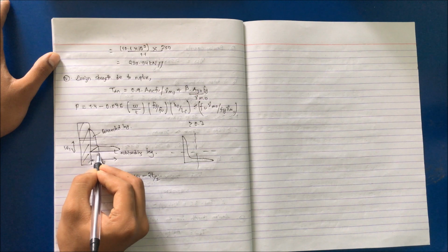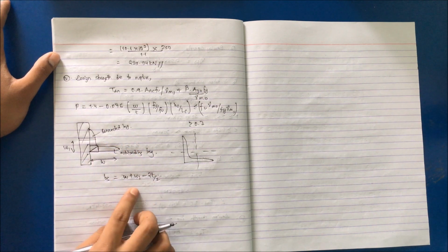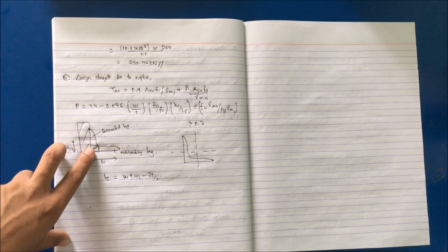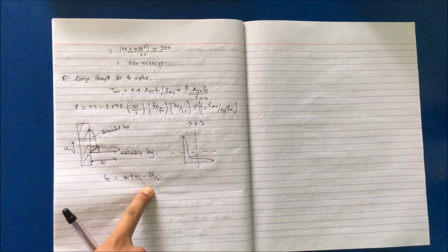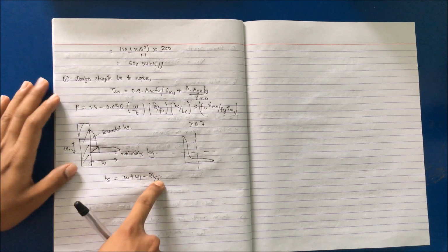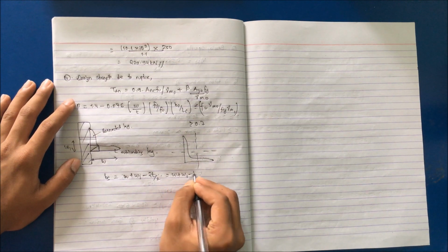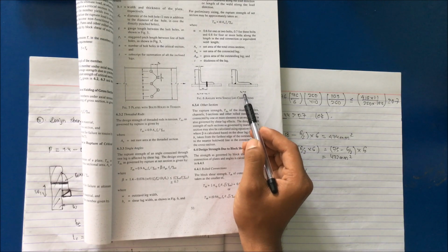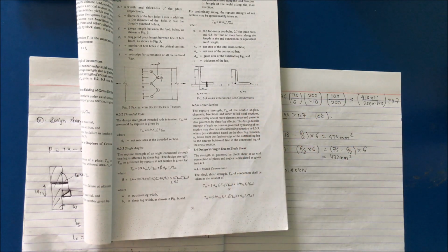One of the thicknesses lies in the outstanding leg and one thickness of the connected leg is reduced. This part won't face shear lag. So finally we'll get Bs = w + w1 - t. In a welded connection, Bs is equal to w, where w is the width of the outstanding leg. That is the difference.